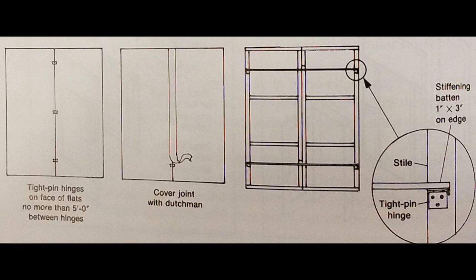There are some times, though, in which a unit may have a hinge piece in the middle, and this may just be for transportation purposes. But once you get to the final staging place, you can add what is known as a Dutchman to cover one of those joints, as you can see in this middle section here. That Dutchman is a small piece of fabric or a thin piece of material that goes right over the seam and sometimes those hinges, and it breaks up that hard looking edge and allows you to paint over that Dutchman to touch up any of the color of the wall itself.